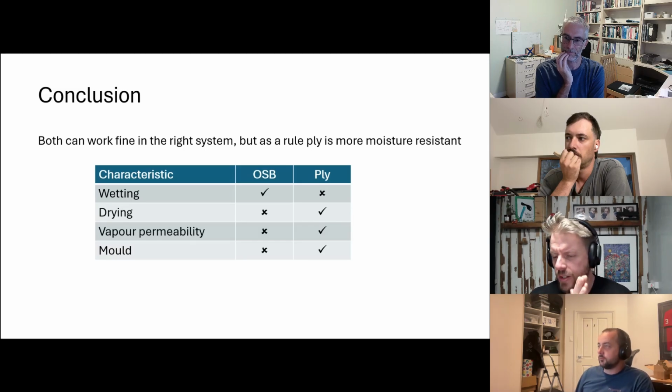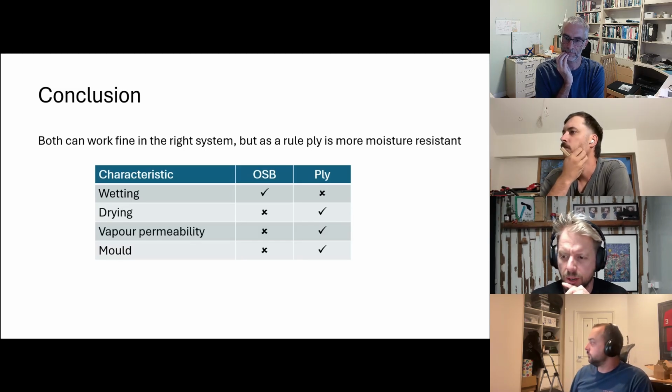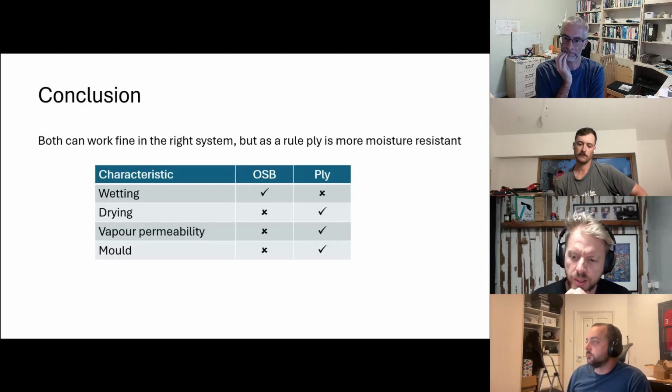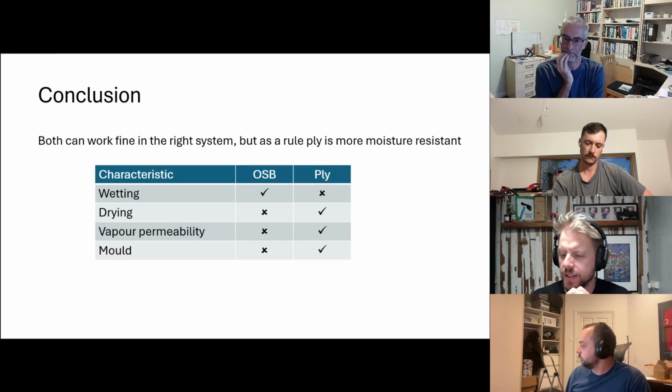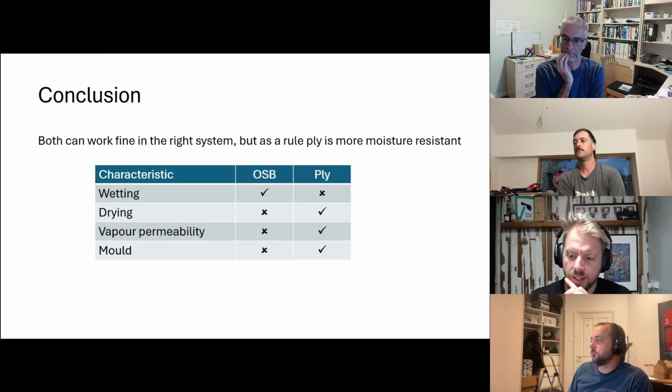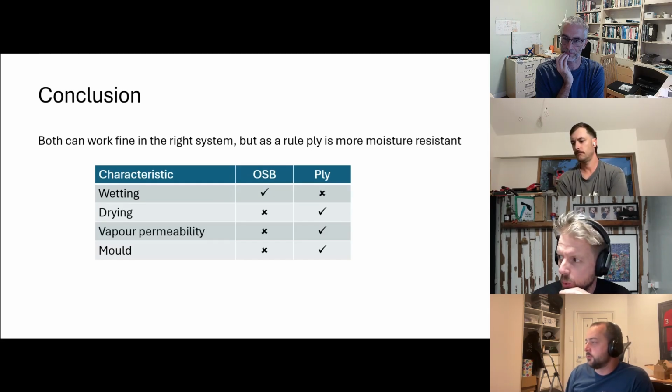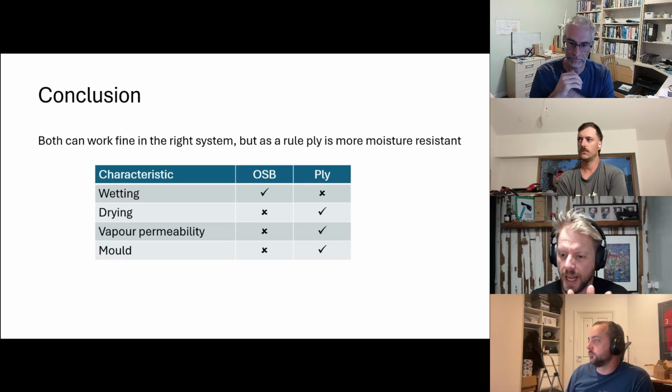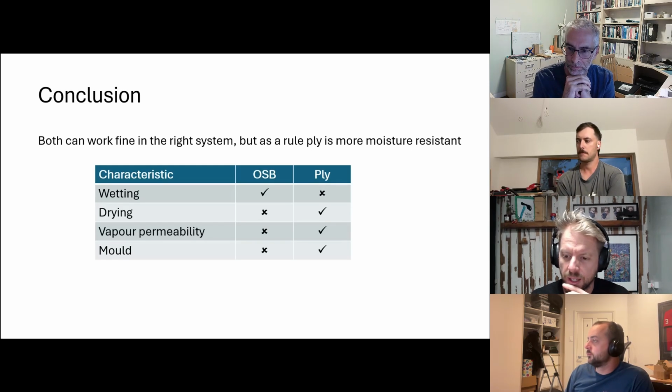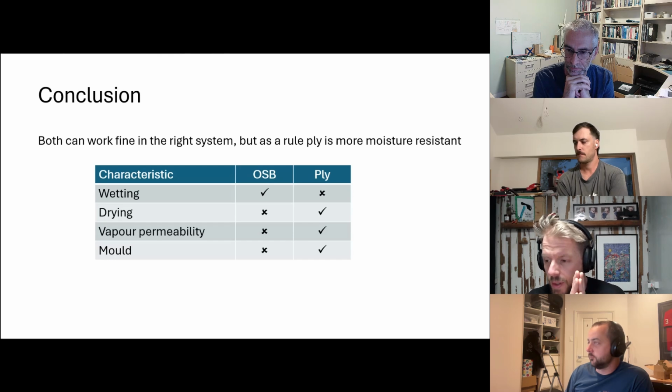I can only answer it intuitively, Saul, from my side, and that is that it's just not what we're used to. I know that full sheathing is practiced all over America and in a lot of parts of the UK and Europe. I just think it's something that we haven't adopted. I think it's a great way to have a super strong building. And also, Cam, you could probably add to this, if you do a peel and stick layer on the outside, you can actually get your air tightness from the outside, arguably not having to put it on the inside.